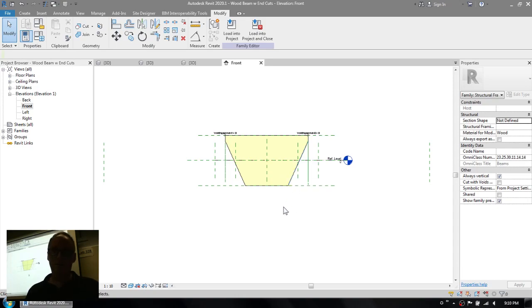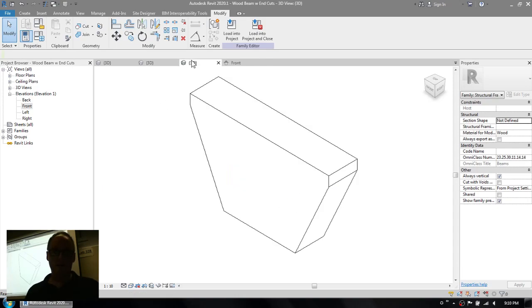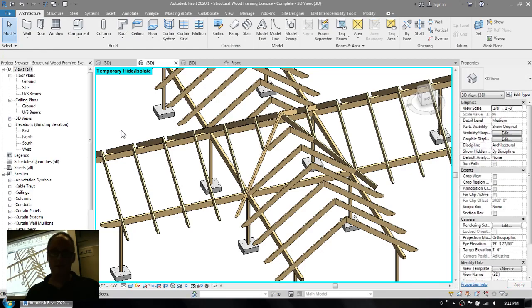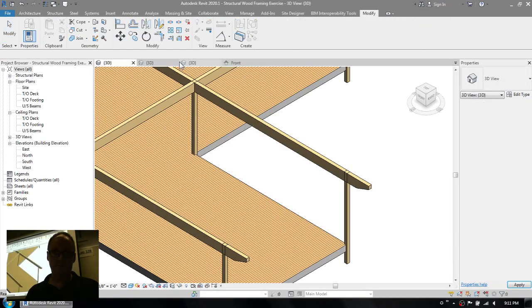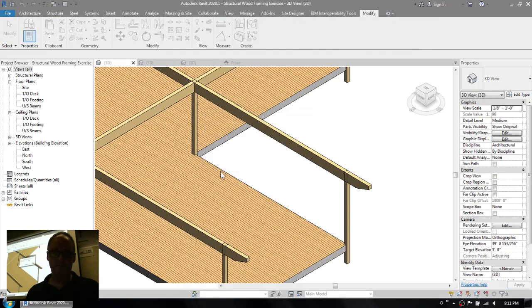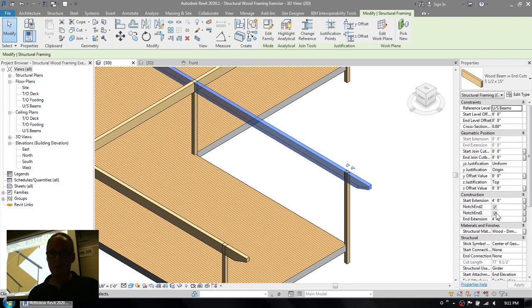So what those checkboxes do that you see in our model here, they move the voids in so that they carve those beams. When you uncheck these boxes, it moves the voids away so that they don't cut the beams. So the out-of-the-box beams don't have these. And you folks are welcome to take those beams that are in that folder and use them in your own practice.